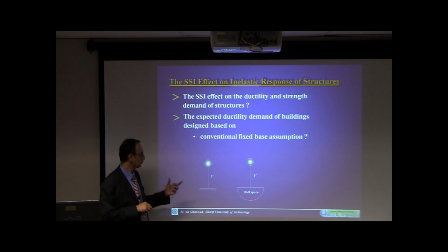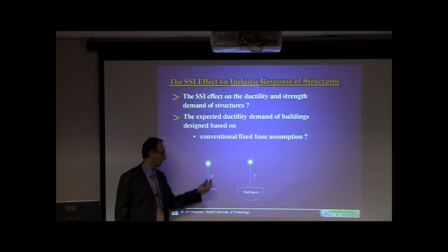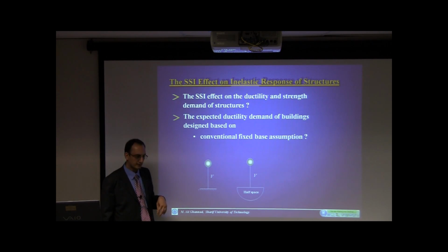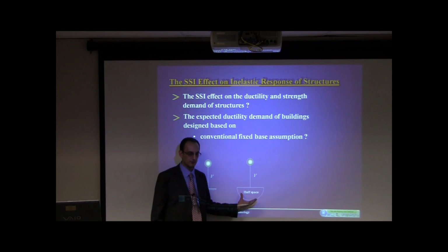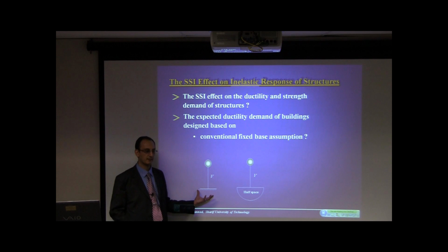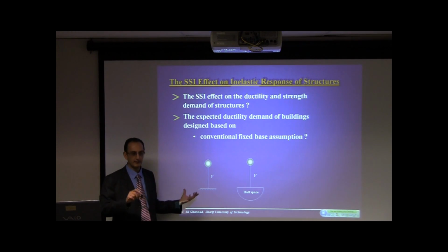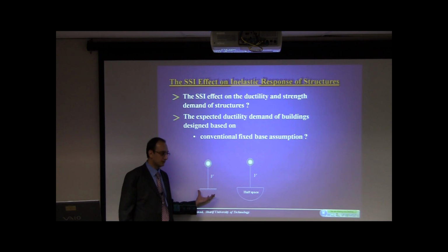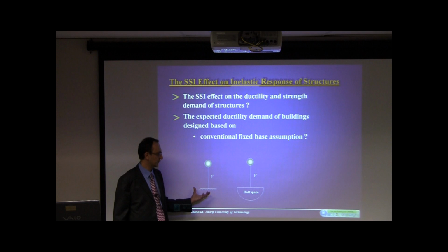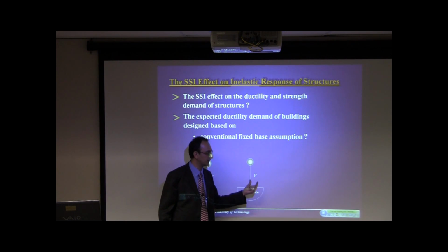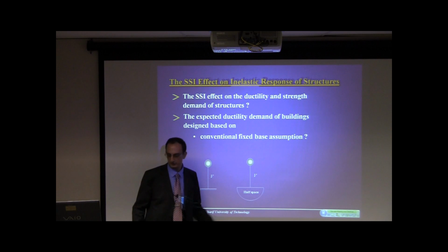It means that usually we design structures and find a base shear according to codes. But in reality, it's located in the half space in the soil. So usually, if we use dynamic analysis, for example going to the inelastic dynamic analysis, we expect the results from this model. Okay? But in reality, this is the case. So we have to see what is the response of this system.